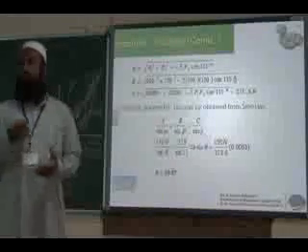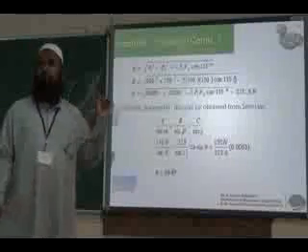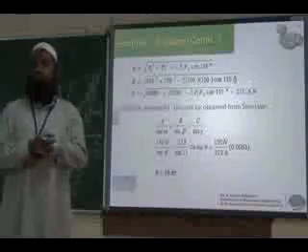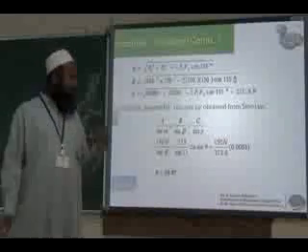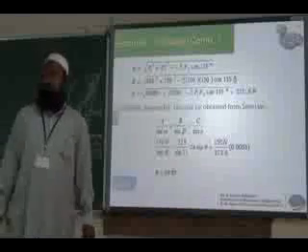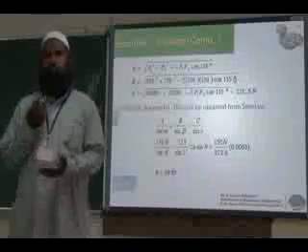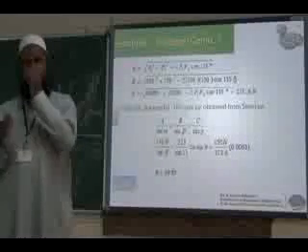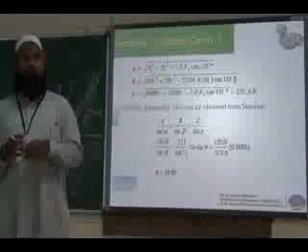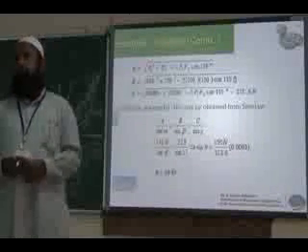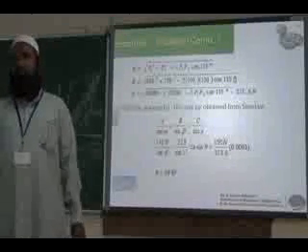So using the cosine law and sine law, we can numerically obtain the resultant's magnitude as well as direction. Any doubt? The main part is determining the angle. If you understand the angle, then you can go for applying the cosine law and sine law to get the unknowns.